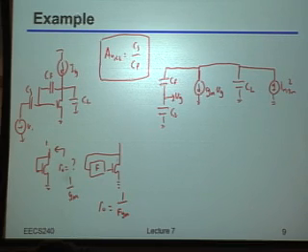Same idea here: if I move this drain voltage around, that's going to move the gate voltage by F times that movement, which means the current I get out of it is F times GM. So in particular, if F is less than 1, my impedance is going to be higher by that factor of 1 over F.